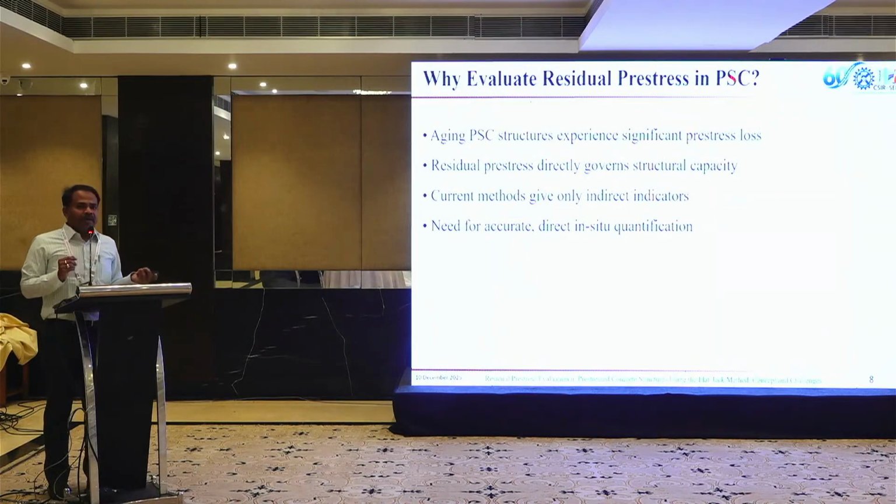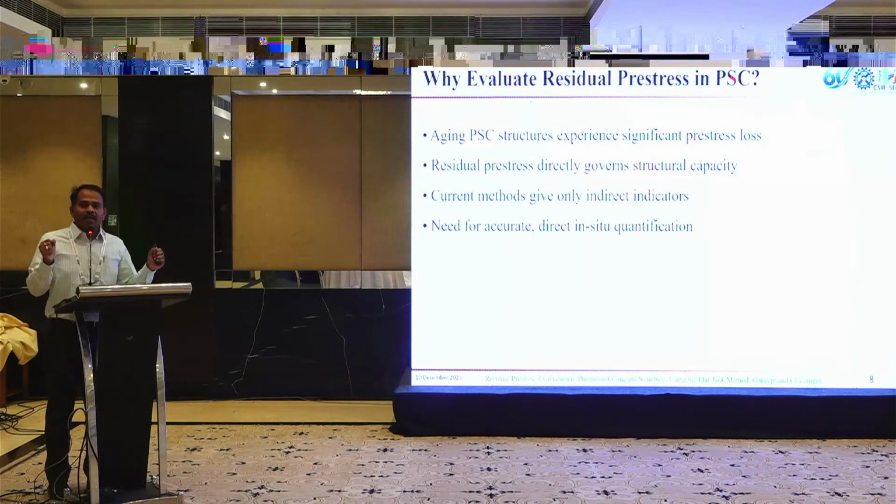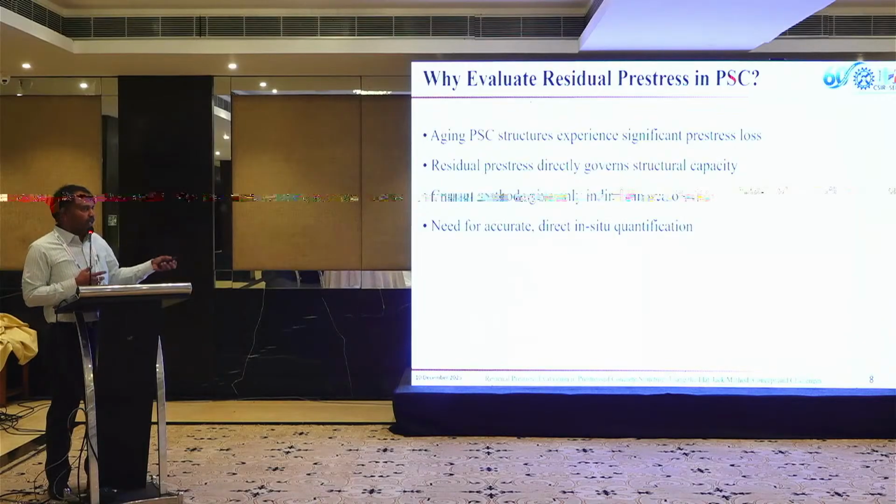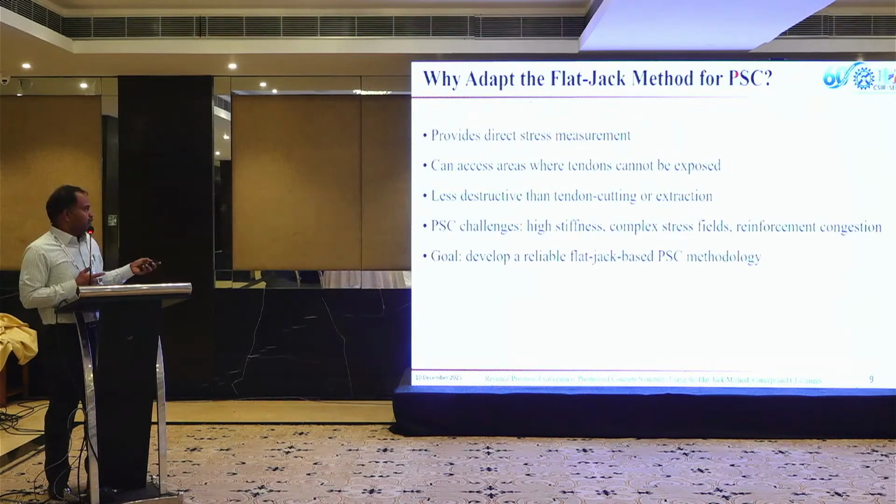So why evaluate residual pre-stress? For a long time, it relaxes. Then the force in the rubber band reduces. Because of this, the compressive stresses reduce, tensile stress increases, and cracking and deterioration happen.